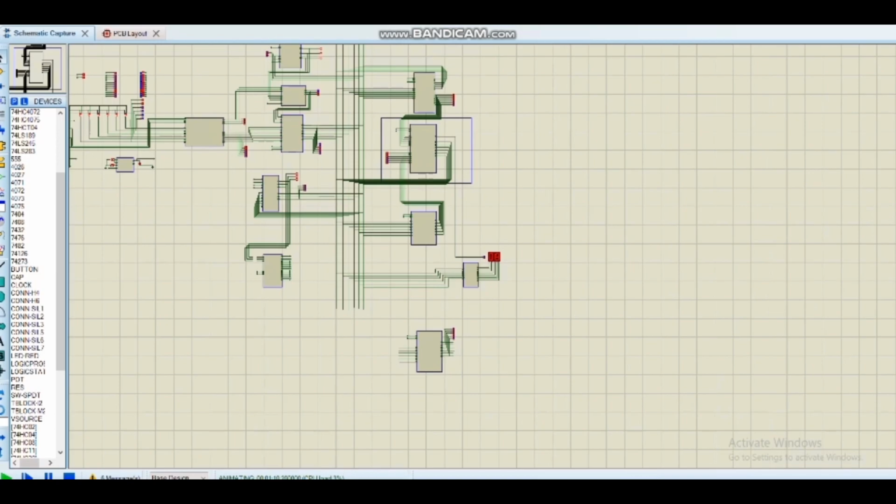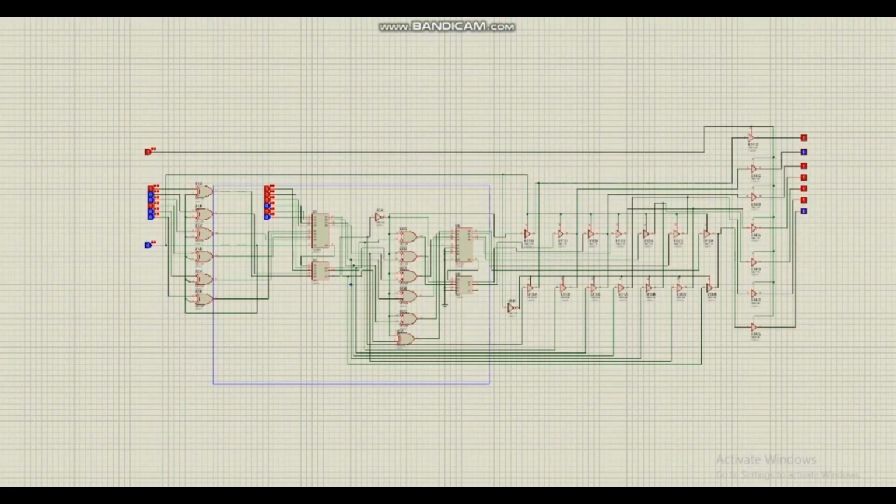To address one of our improvements, this is my design of the ALU, or arithmetic logical unit. I introduced the external sign bit operation, so we can also see whether in a subtraction operation it is a positive number or negative number. To see that, if I go through it, first of all we used a normal 4-bit parallel adder, and then we used 6 of them, so it can add 6 numbers.